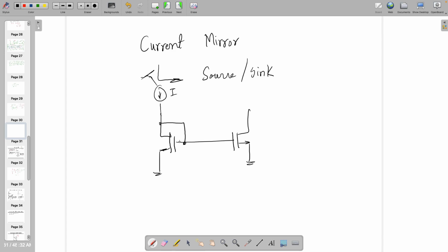So if I pump current of, let's say, 10 micro, and if this W by L or some value is given, then how to make it 40 microampere? 4W by L. So 4 is actually the multiplier, and make the same thing.